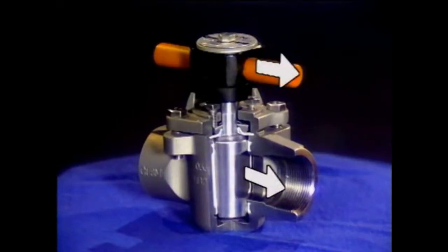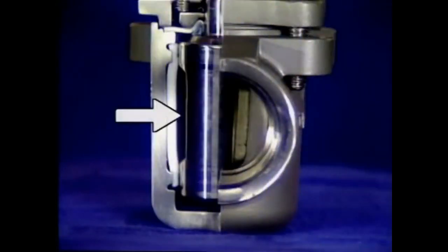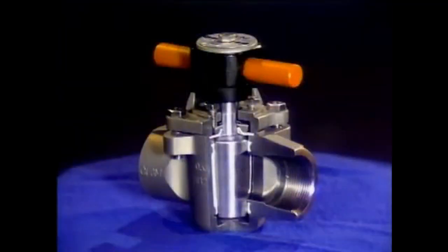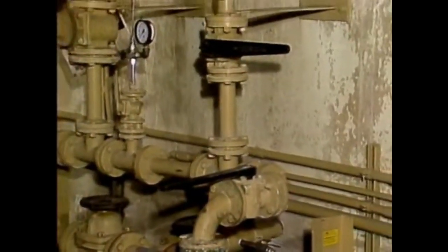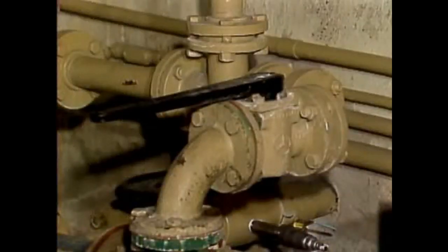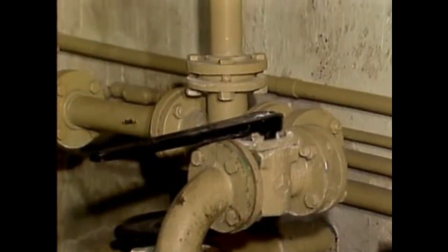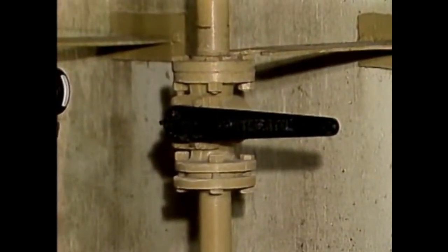When the opening in the plug is in line with the valve's inlet and outlet, the valve is fully open. To close the valve, the plug is turned so that the opening is perpendicular to the valve's inlet and outlet. So a plug valve can go from fully open to fully closed with only a 90-degree or 1/4 turn of the handle. Also, the handle on a plug valve is usually aligned with the opening through the plug, so that the handle position indicates the valve position. If the handle of the valve is in line with the piping, then the valve is open. If the handle of the valve is perpendicular to the piping, then the valve is closed.